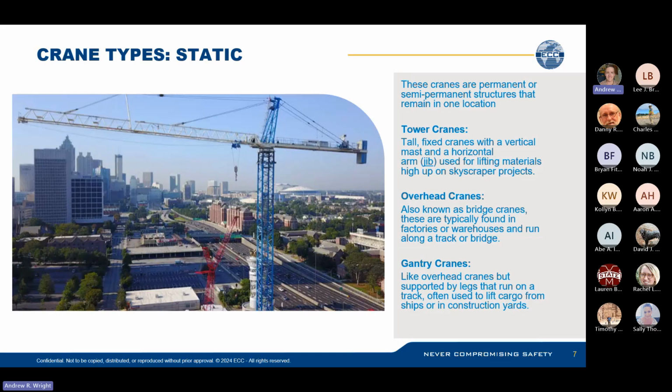A side note on gantry cranes: they're pretty common in hangars. So if you have any jobs inside airplane hangars, you might come across a gantry crane, and you should always lock them out if you're going to be working near them, because a unique hazard is that some of them have open electrical bus bars that power the cranes and go along the track, and if you touch those and they're not shielded, they could shock you. So make sure that if you're working near them, they're locked out.